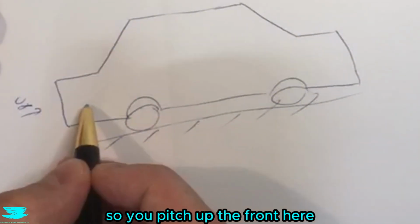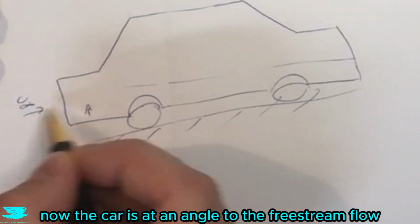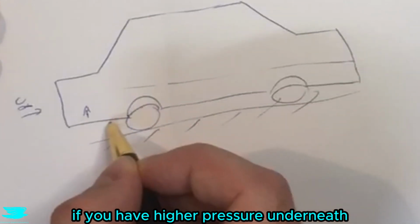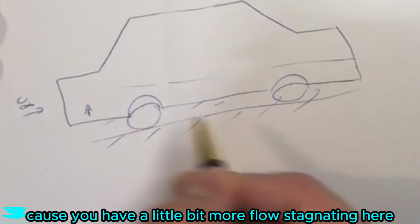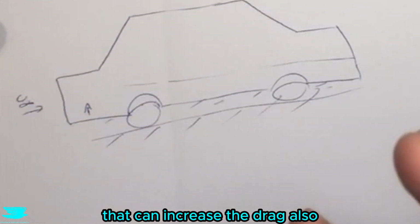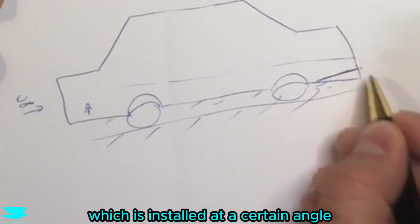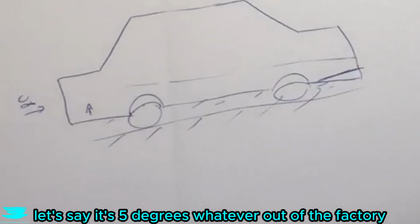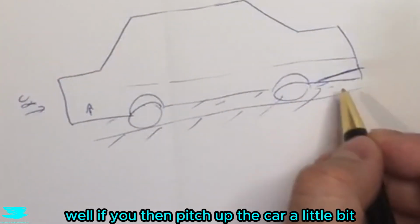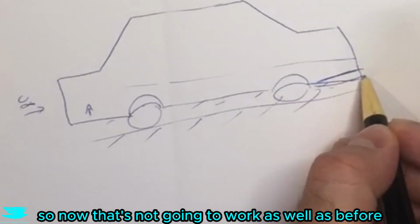So if you pitch up the front here, what happens is now the car is at an angle to the free stream flow, and depending on what's going on top, if you have higher pressure underneath because you have a little bit more flow stagnating here and low pressure on the top, that can increase the drag. Also, now that we have the diffuser, which is installed at a certain angle, let's say it's 5 degrees or whatever out of the factory, well, if you then pitch up the car a little bit, that diffuser is now at a lower angle. So now that's not going to work as well as before.